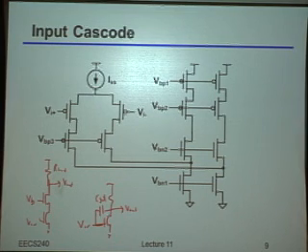Well, indeed, one of the nice benefits of a cascode is that to the extent that that source node there is indeed a low impedance node, the gain across there should be low, and therefore you really shouldn't be paying much of a penalty on that CGD. So even in something like this common source resistively loaded amplifier, where maybe you didn't want a ton of gain, you'd add the cascode simply to reduce the multiplication of that CGD. It's going to turn out that this is exactly the reason we're going to want to do this here.